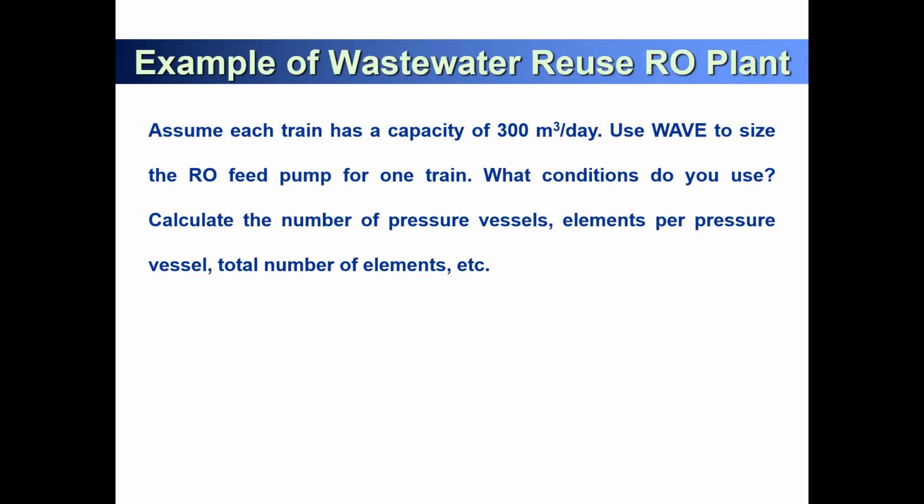So if you recover 50% of water, you increase only 2 grams per liter of brine, right? So in fact, you can increase more, up to 80%, 85%, potentially 90%, because wastewater quality is relatively low TDS. So we can utilize the high recovery rate.